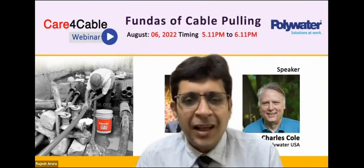For example, if you are pulling a cable of 80 kilometers, and if you go by the regular formula, the number of joints will be multiplied by 2. 500 meters is the cable length. But if you increase the length by 50 meters or even by 100 meters, with some possibility, the number of joints can be reduced by 20%. And that can increase the asset infrastructure life and things like that. Very good advice.